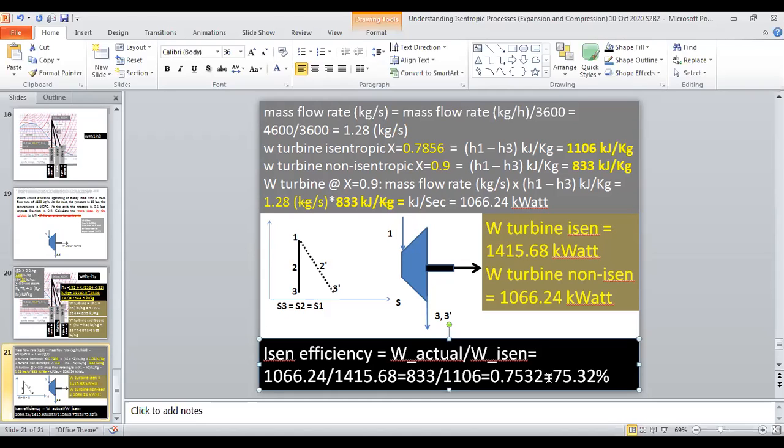So you can look into the literature to see how good the isentropic efficiencies are for turbines, compressors, and even engines. Even for refrigerant compressors, for the best compressors, you can consider 80% reasonable. 90 may be too much.